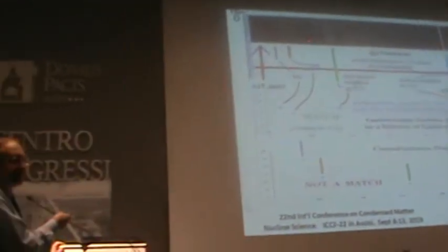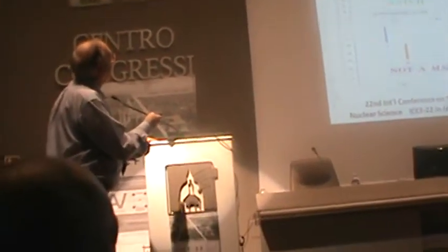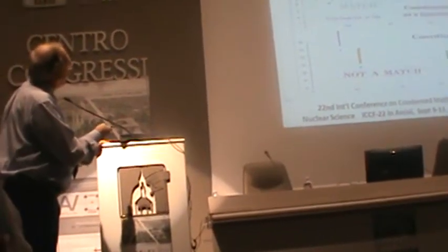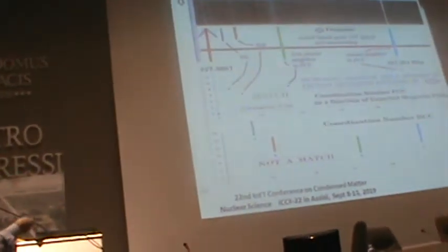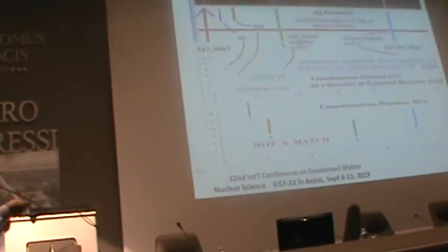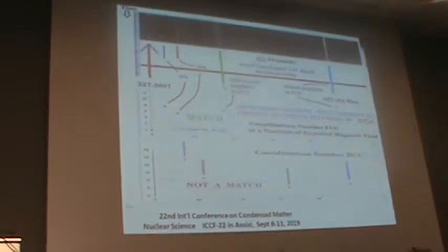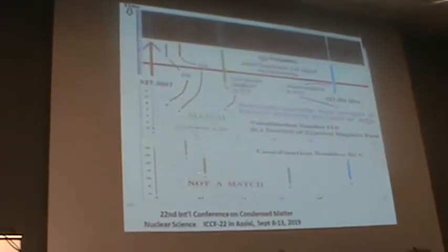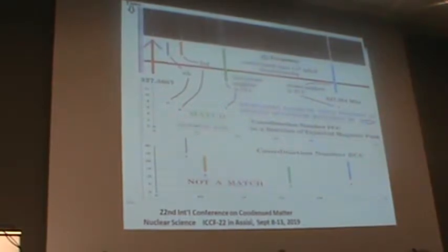Hey, this is interesting because a singlet, which we expect, has become a triplet. We'll talk about the implications of that in a second. And here's the third and the fourth closest. And we get a nice match for face-centered cubic. This to this, that to that, this to this, matching that to that. And over here, again, it's a very small distance and frequency. Let's look at the body-centered cubic. It's no match at all.